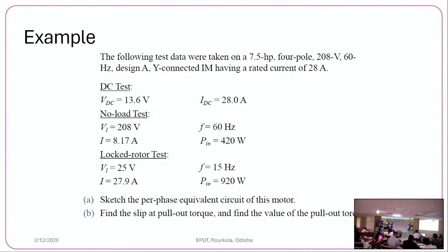Sir, the frequency is given as 15 hertz, but it is not required. Sir, actually it is locked by belt and pulley, therefore it is rotating? No, in the blocked rotor test the machine is not rotating. Blocked rotor means not rotating; it is always locked. So you get Z1 by this expression.